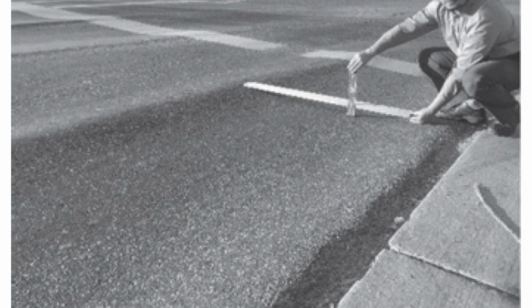Causes. Rutting occurs in 3 basic ways. Wearing of asphalt surface. Vertical deformation of layers, also called structural rutting. Shear deformation of asphalt layer, also called instability rutting. Wearing of asphalt surface is the progressive loss of material from the roadway surface due to poor quality asphalt mixture, studded tires, and inadequate compaction during construction.